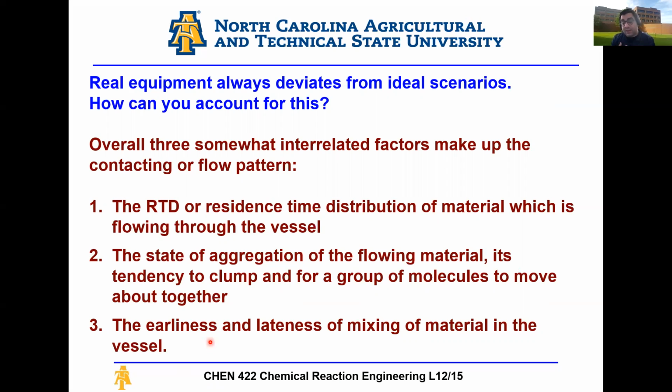And the third is the earliness and lateness of mixing of materials in the vessel. This point is really important when I have multiple reactants entering a system. At what point am I mixing these reactants? At what point am I introducing them, putting them in contact with each other? And this really becomes important when you have multi-phase reactions.